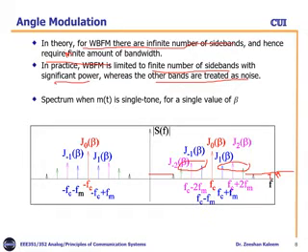So the spectrum of wideband FM, for a single tone, is for a single value of beta. For example, we have a fixed beta and varying n. So here we have n equal to 0, 1, 2, so FC, FC plus FM, and FC plus 2FM. There are three significant bands, and the amplitude of these bands depends on the coefficients J0 beta, J1 beta, J2 beta.